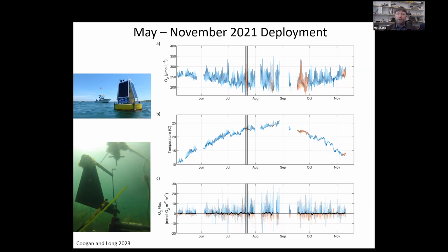What you see in the oxygen signal is it starts relatively high with low variability, and that's low water temperatures causing the concentrations to be higher, but also less productivity at those times of the year. As you move into August and September, you see the oxygen concentration goes down, simply a function of temperature, but also that daily variance increases substantially due to primary production and respiration when the waters are warmer. And then going into the fall, you can see the variance again decrease.